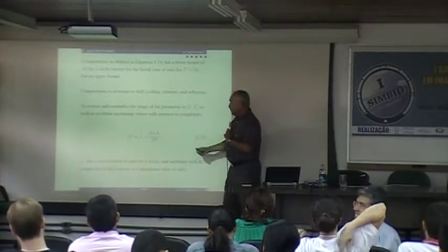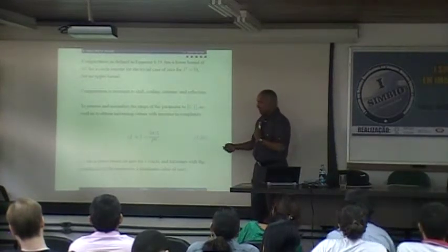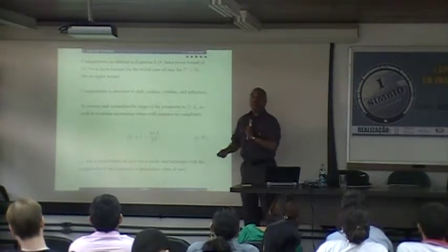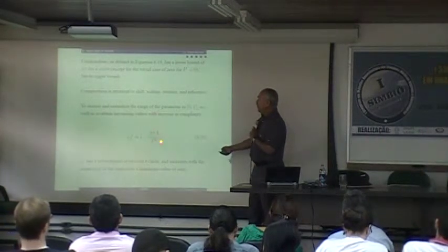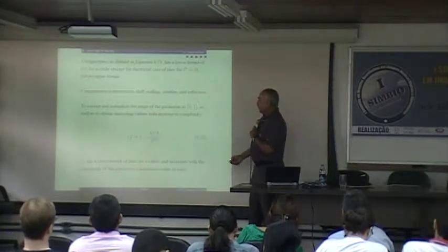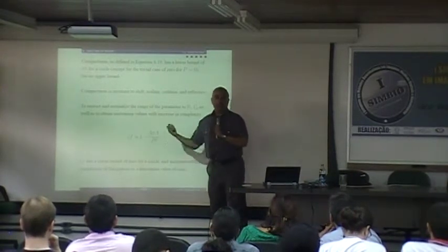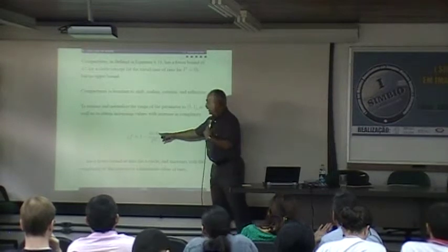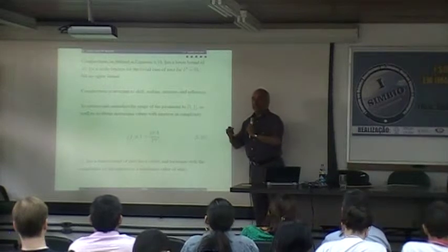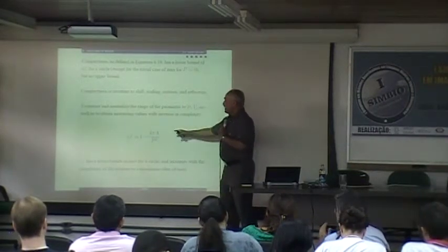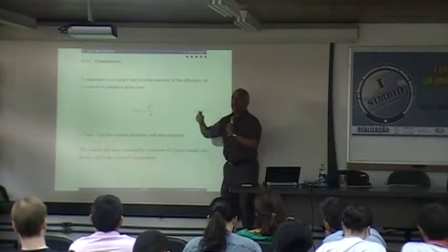I can normalize that: 1 minus 4 pi A divided by P squared. So this is better. It is limited to the range 0 to 1. When P is very large, A is very small, goes to 0, this is 1. And for a circle, this is 1, so this is 0. The total shape factor is 0 for a circle, and 1 when either area is 0 or perimeter is infinity. Within practical limitations. So this is advantageous, whereas this, as area becomes smaller and smaller, becomes very big.